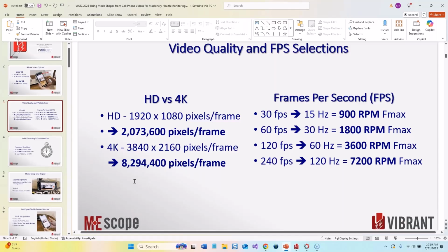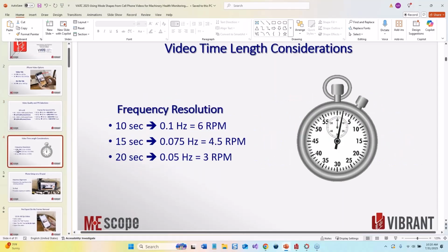The phase difference between the top and the bottom of the video is so small that you can just assume it's simultaneously acquired. So you don't need to spend a lot of money for a fancy camera. And 8 million pixels per frame. That's almost like having 8 million accelerometers measuring two-dimensional motion in the frame of the video. So a lot of resolution.